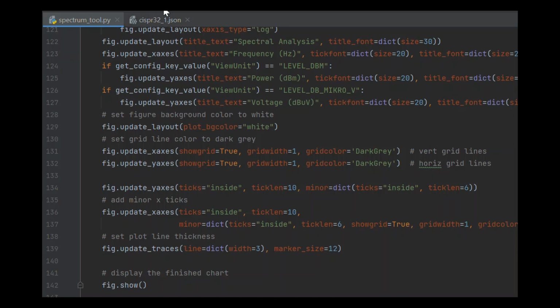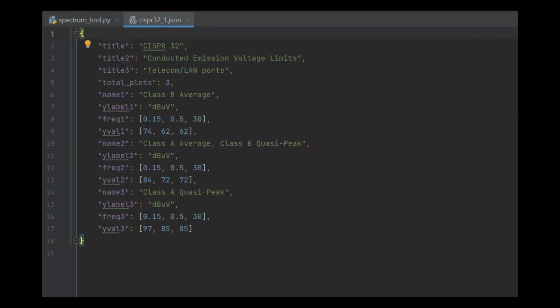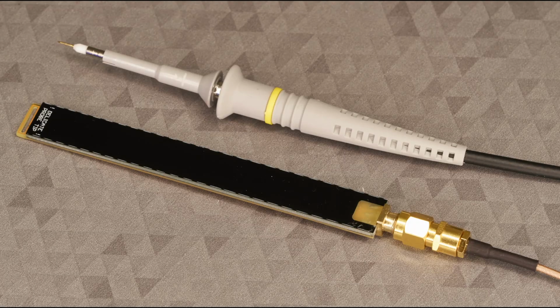Anyway, this shows great signs that it is worth improving this test bed, because the ability to quickly test circuits for emissions during development definitely seems feasible with the MXO. For radiated emissions testing, the 500 MHz limit to the MXO license that I've got is definitely a limitation, but as mentioned earlier, it can still provide value to show some of the emissions with harmonics that may have frequency content within the scope bandwidth.